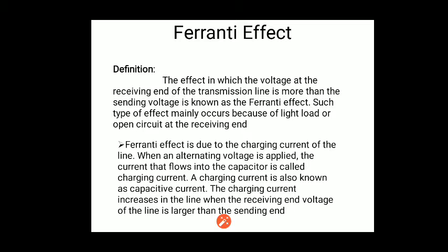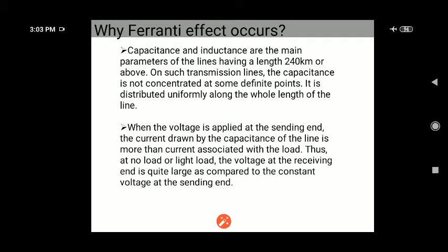The Ferranti effect is due to the charging current of the line when the alternating voltage is applied. The current that flows into the capacitor is called the charging current. A charging current is also known as the capacitive current. The charging current increases in the line when the receiving end voltage of the line is larger than the sending end voltage. This effect is known as the Ferranti effect.